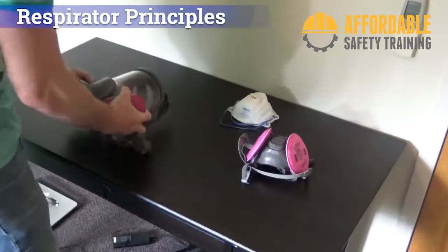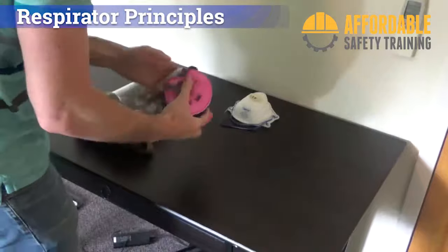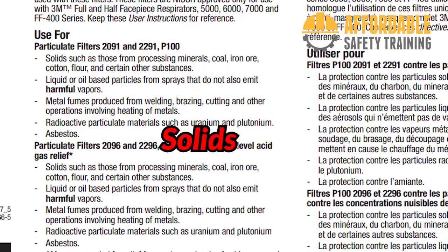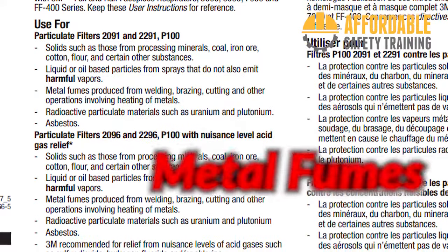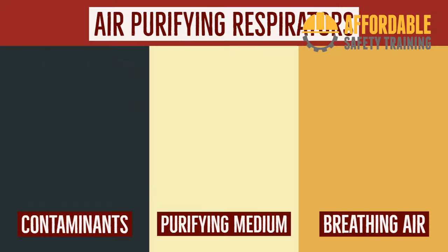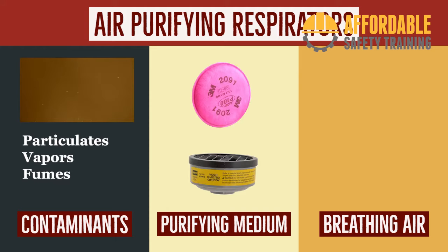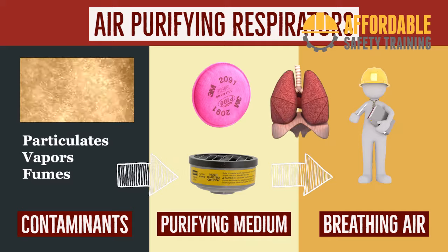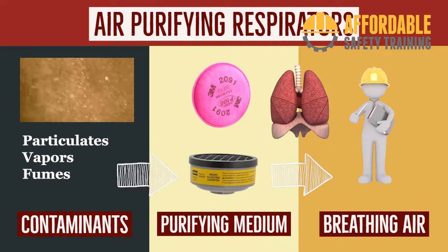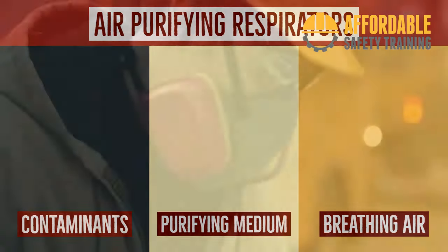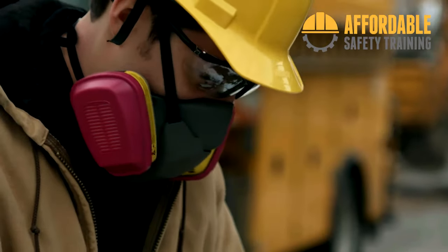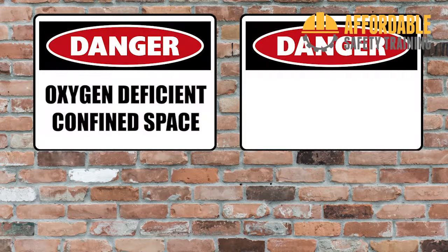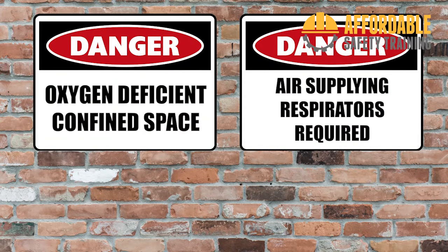There are many different kinds of respirators, cartridges and accessories. It is important to select a respirator that is designed to protect against the atmospheric hazard that is present in the work area. Air purifying respirators use filters or chemicals to remove contaminants from the air. Unless powered, the air is passed through the filter with the force of the user's breath. This can lower the effectiveness of an employee by increasing the energy that is required to breathe. Air purifying respirators will not work in low oxygen environments.